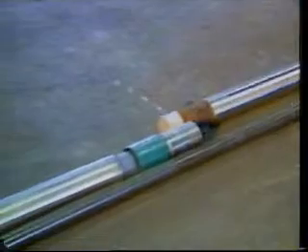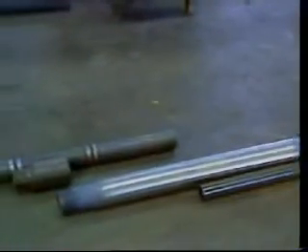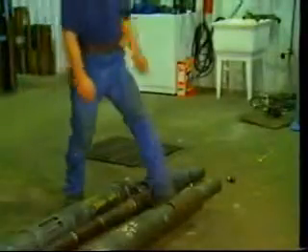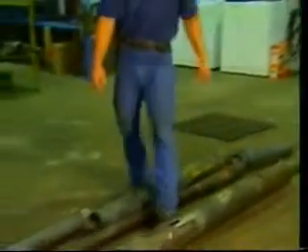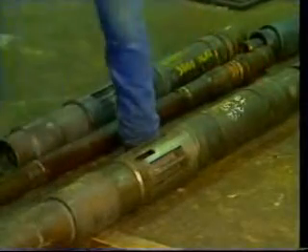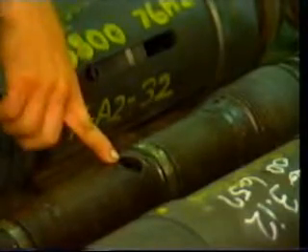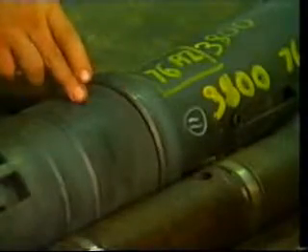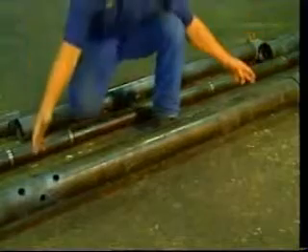The usual downhole components of a gravel packing operation are included here. Let's review the components, beginning immediately below the work string with the setting tool crossover assembly. The setting tool crossover assembly is secured to a packer. During running in and squeezing operations, the bypass port in the crossover tool assembly is positioned within the packer. Slips secure the packer to the casing. Below the packer is the perforated extension.